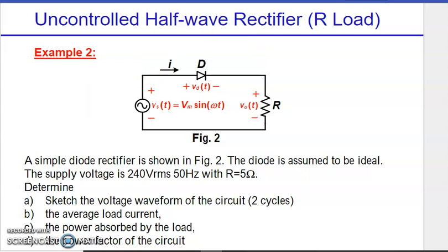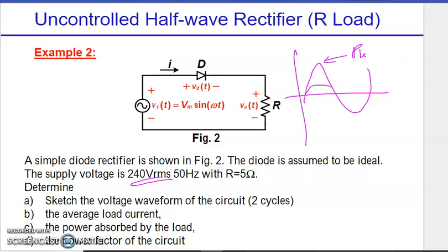Now, what is given here is the RMS value. Later, if you simulate, it will show you the peak. So this is peak, not RMS, and the voltage is peak, and the current is also the peak value. So you have to take note.